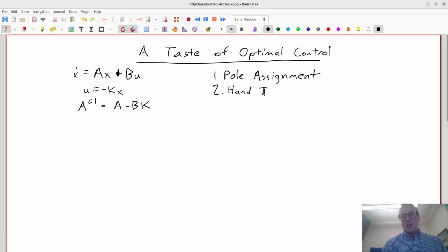So if we couldn't calculate the gain values by hand, we might just have a simulation of the system, and we would change the gains and adjust the damping as we could see in the response or how the eigenvalues moved, and just do that manually and heuristically. And then the third technique that we used is drawing or plotting the root locus.